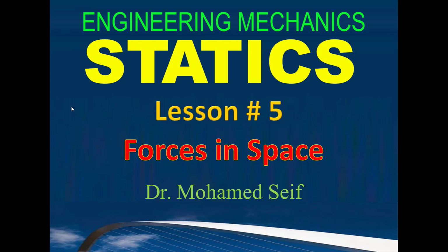are in equilibrium, how we can solve the equations of equilibrium, which means that the sum of the force components in the x direction should be equal to 0, the sum of the components in the y direction should be equal to 0, and the sum of the components in z should be equal to 0. Also, how to get the components from the beginning once we know either the angle, the direction, or the two points on the direction of the force in space.